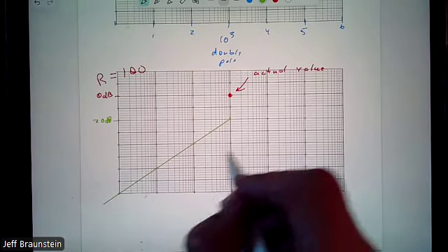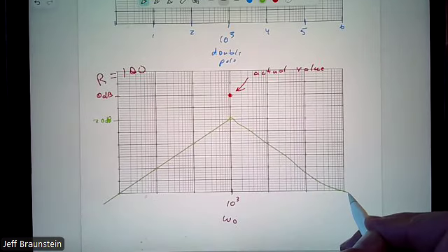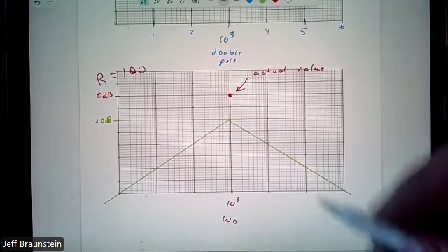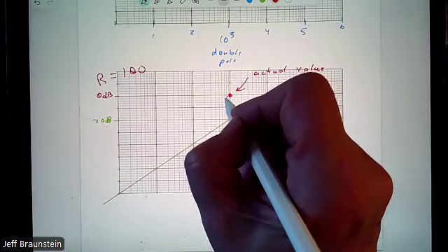Finishing up relatively quickly. I can do this in the last 30 seconds. There's my straight line approximation. Normally I give you a little bit more rules, but I'm just demoing this, not on the test, but it's something that's worth noting. Actual value, straight line approximation. As we are far away from poles and zeros, straight line approximation is always valid. Close to the pole and zero, we do some sort of fitting.